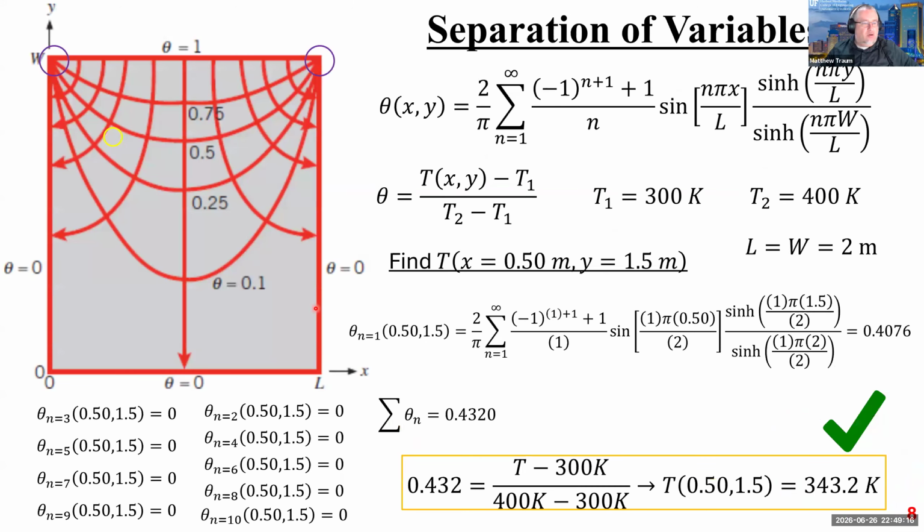Okay, so how cool is this, right? How cool is this? This is what it looks like. So, right, here's my constant theta equals 0, constant theta equals 0, constant theta equals 0. Here are my two discontinuous spots, right, which I told you I would point out. So we're going to ignore the temperature at this corner and this corner because those temperatures are simultaneously theta equals 0 and theta equals 1 because of the way we set the boundary conditions, right?